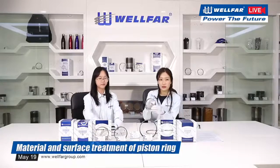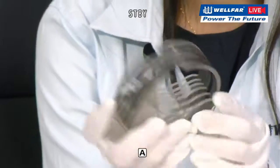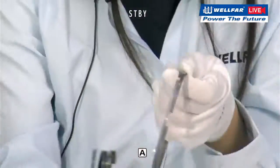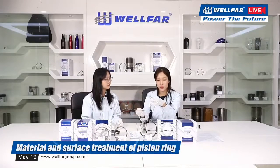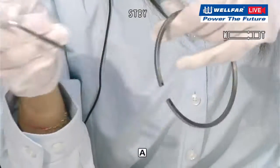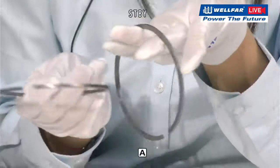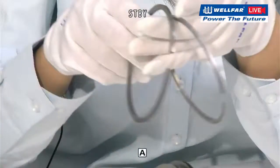Yes, this is the piston ring for Mercedes-Benz OM352. We can see the first ring is made of KB1. This is the first ring. Do you know how to distinguish KB1 and alloy? We can distinguish by its sound. Yes, I can hear the sound. This one is the first ring made of KB1. The sound is clearer and more melodious. So the ring made of KB1, the sound is clear, right?